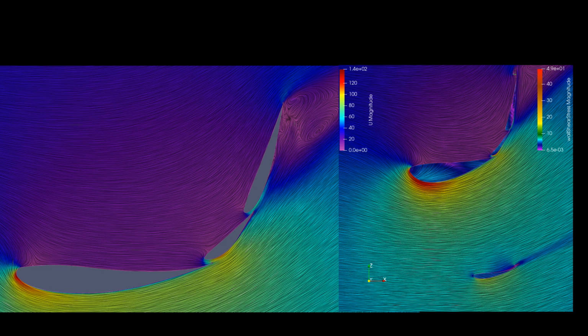This rang so true. I thought I was getting close to a result, and the numbers seemed okay, not great, but okay. It seemed that the flow was mostly attached, but then a slight tweak and I would get an additional 200 newtons, and the flow becomes obviously attached, going by the wall shear stress map.